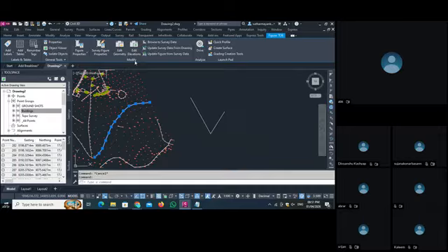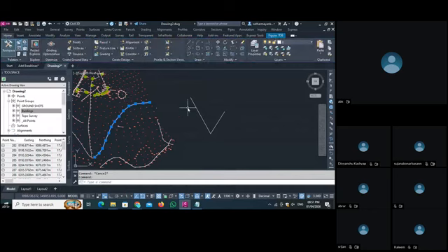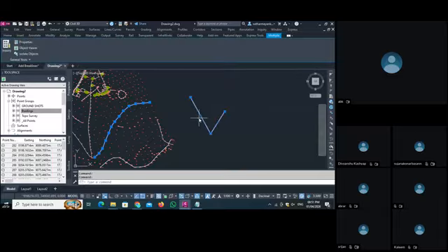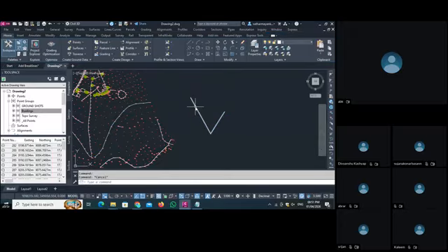So we have access to the modify tools. Especially today I want to talk with you about these things, Edit Geometry and Edit Elevation. These two are very important things. As you know, in the starting we talked about the Draw and Modify bars for the 2D lines. As we select the 2D lines, there is no change here. We can change this line from these two bars.